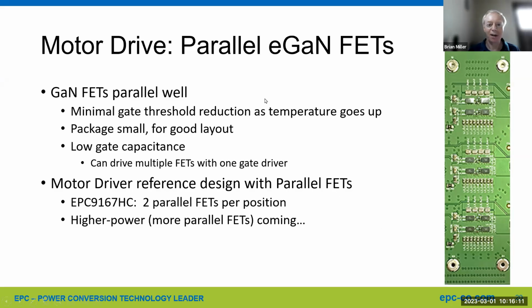motor drive. Can you parallel eGaN FETs? How does it work? How do you do it? This is a clip from one of the evaluation boards on the previous page. 3 phases. You can see 4 FETs per phase, so it's 2 in parallel on this particular board. All the details are available on the website from the previous part number.